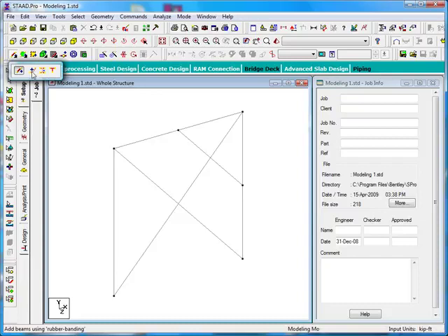So to demonstrate in this case, I'm going to choose the third one in from the left, which I know to be the Add Beam Between Midpoints tool. That tool now becomes the active tool on that button. Notice that it doesn't automatically become activated though. In order to activate that tool, I need to come back up and click it. Now it takes on that depressed appearance. We're now in the mode of adding beams between midpoints, and we'll see that this is an even faster way of doing what we just did over here.